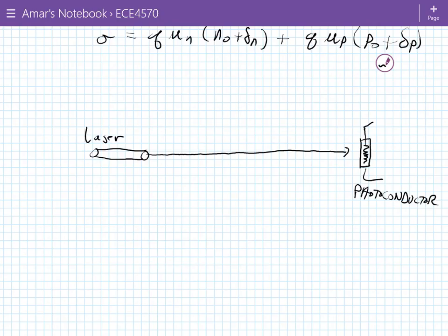If someone were to come and stand in the way, this would block the laser light, right? And so what will that do to the photoconductor? How will that change the resistance? It'll increase the resistance. That's correct, because with light you've increased the conductivity. When you take the light away, you've decreased the conductivity and increased the resistance. So if your circuit can detect that change in resistance, then you have a way of detecting if that beam has been breached.